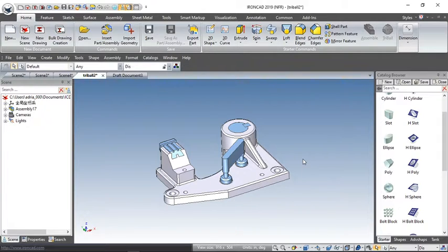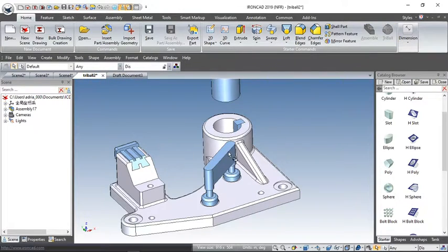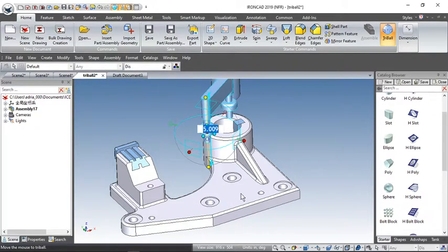Now I can select each individual component. I'll select that component there and press F10, that shaft, key shaft. And I'm simply going to, with the left mouse button, drag the outer handle like so. So I've moved it away from the main assembly, and I press F10 to detach the tri-ball. I'll then pick up this gate arrangement here, F10, and I'm going to lift that up with the left mouse button, dragging the outer handle.